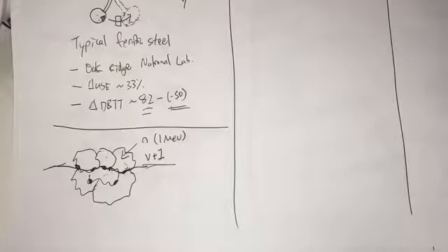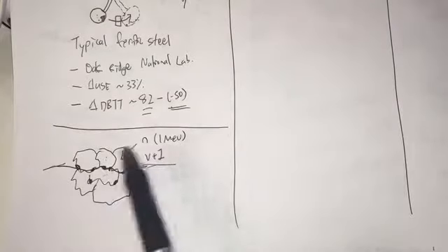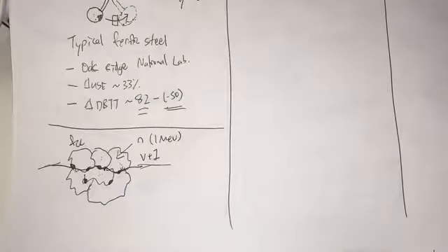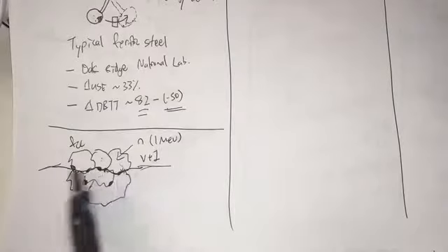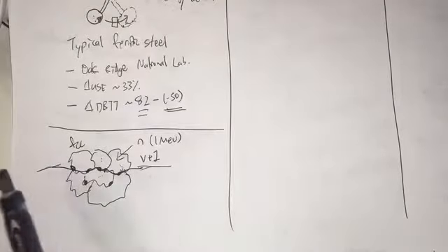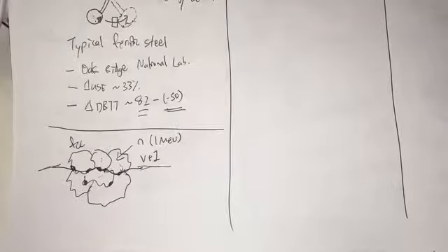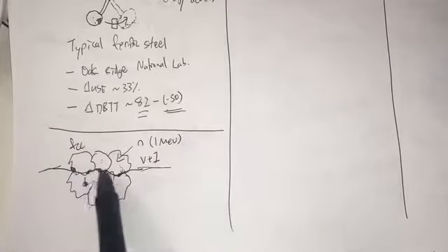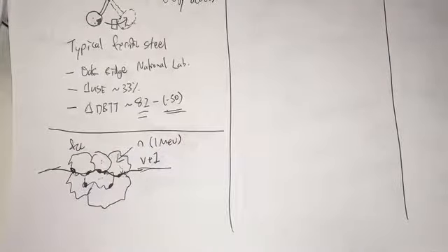So that's what happens when a neutron strikes an FCC material, austenitic stainless steel like SS304. The grains get weakened. The grain boundaries coalesce with the defects, voids nucleate there, and this is where the fracture happens, between grains.